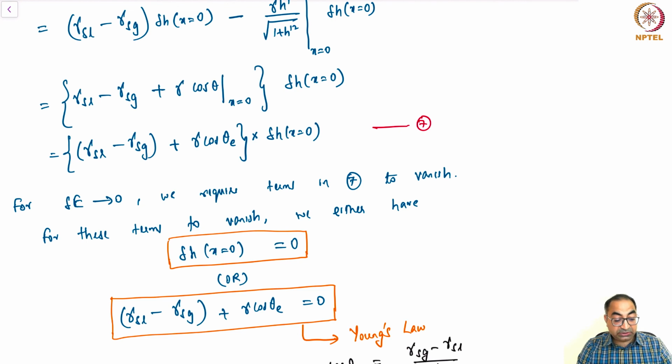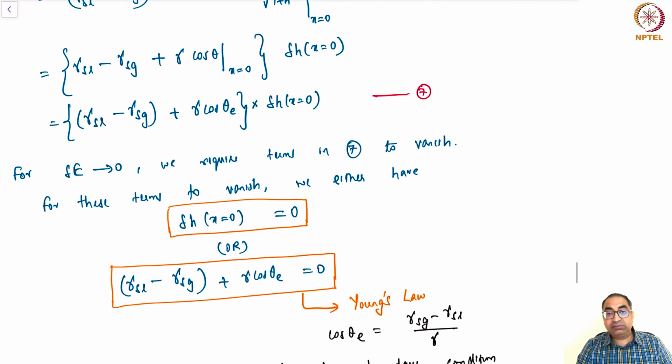Now what we want to do next is to look at problems in wetting. It's interesting that we have ended this lecture on Young's law. What we want to do next is dive a little deeper into the ideas of wetting. We'll be looking at quantities such as the spreading parameter and the contact angle at the wall, and then eventually contact angles on complex surfaces. Much later in the course we'll also look at the contact angle when there is motion, that is, the dynamic contact angle.